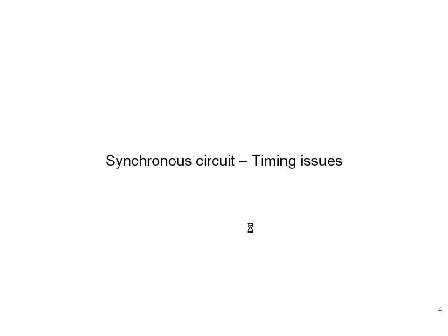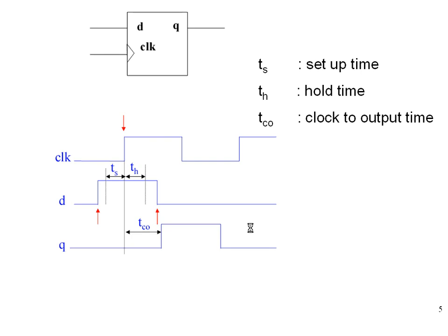That's a rise time. When it comes to synchronous circuits, the definitions of all our timing analysis are based upon three fundamental factors. If you take any D flip flop, any sequential element, you know that on the rising edge the action will take place if it is a rising edge triggered flip flop, but nothing will happen in zero time.